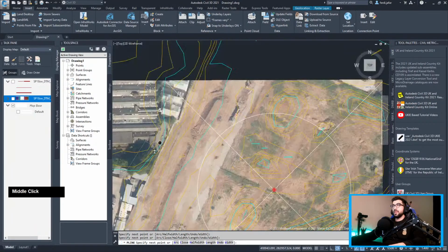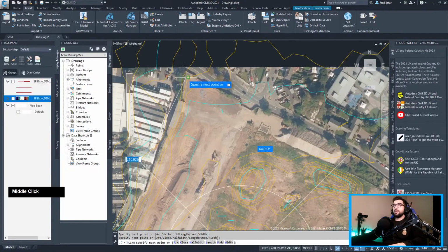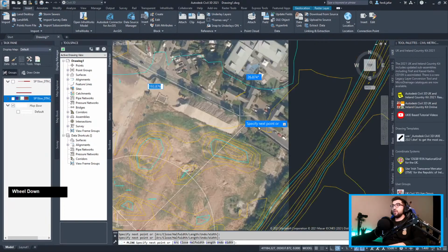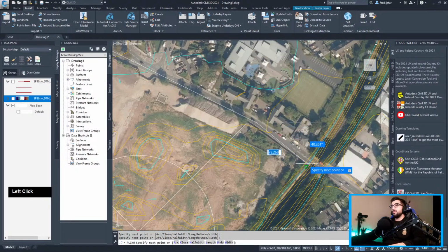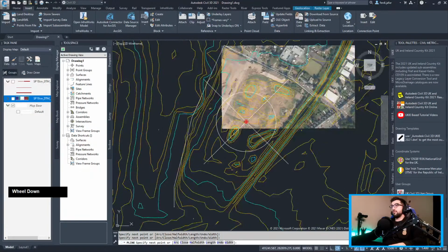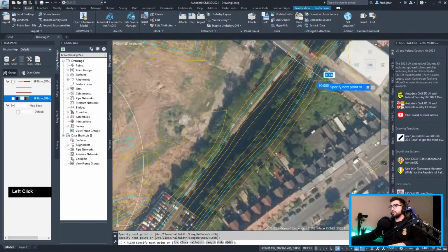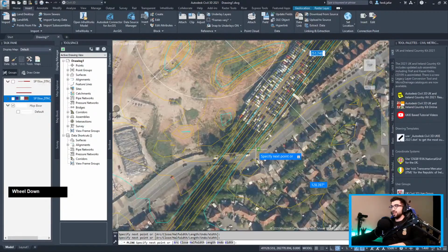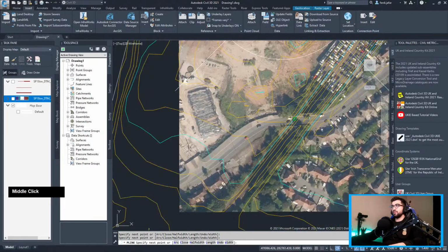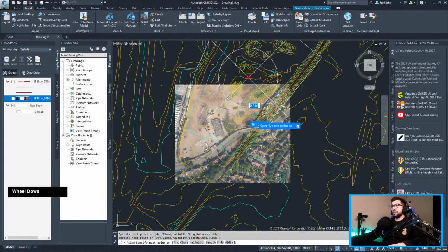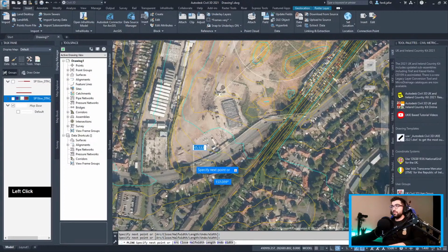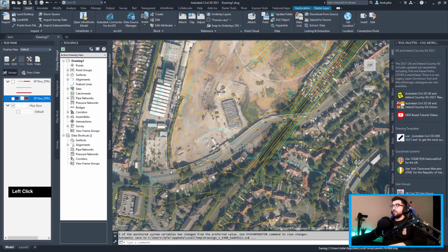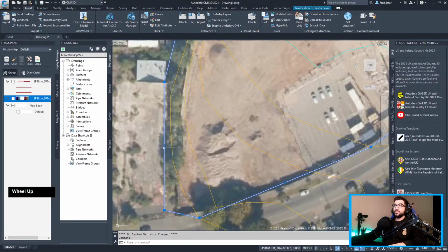And an advice from me personally, if you're gonna be working with the LiDAR information before you have received the topographical survey, I would advise you to offset your boundary line. Actually, let's pull the, what seems like a river. Yeah, or a brook, not sure what I would call it. But what I would suggest is to offset the boundary outside.